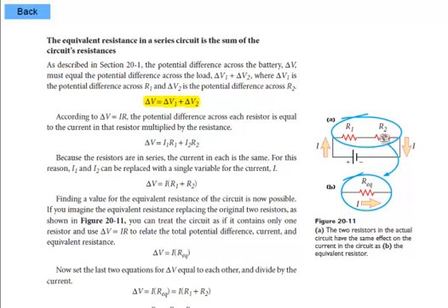And that's where the idea of voltage is coming in. So in my little circuit here, the current through each of these resistors is the same. But the size of the voltage of each of these resistors is based on the size of the resistance. More resistance, greater voltage. Smaller resistance, less voltage. And the sum of the potential difference across each resistor better equal that of the battery or be close. We talked about the idea that with rounding it might be a little off. But if you've got a 9-volt battery and you solve for potential differences, add them together, and you've got 13 volts, you've done something wrong.